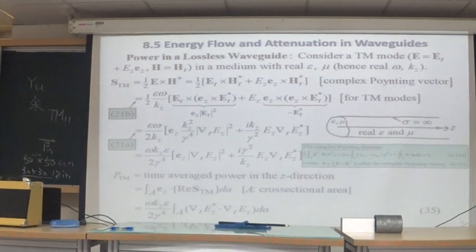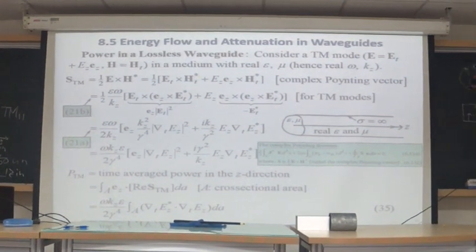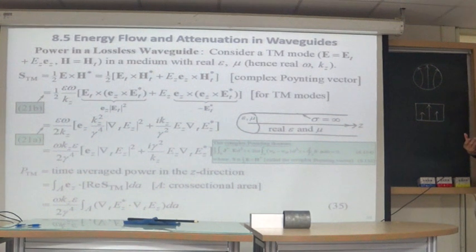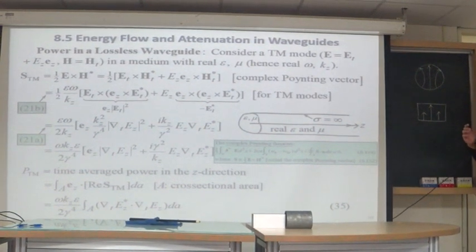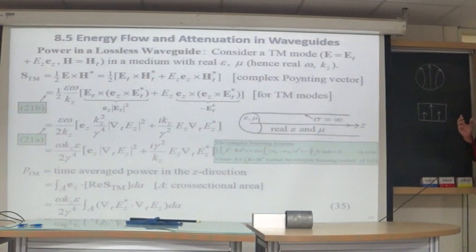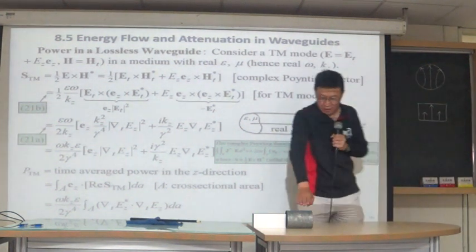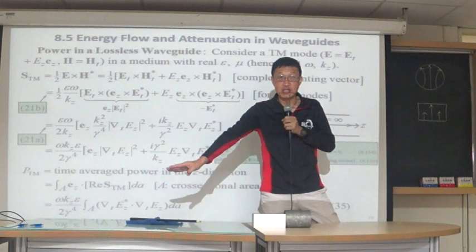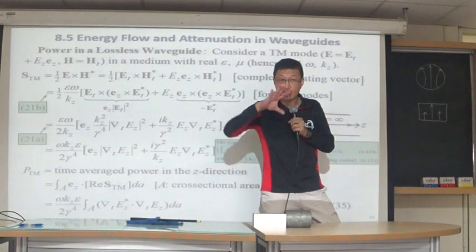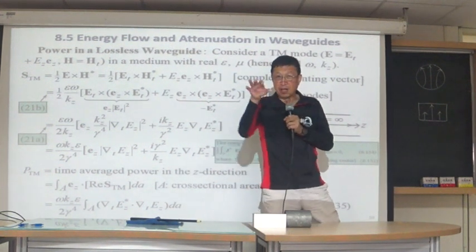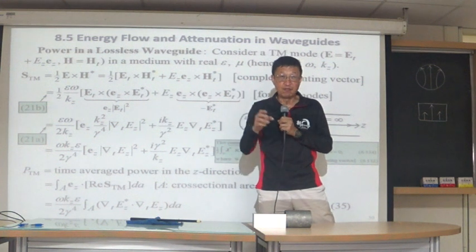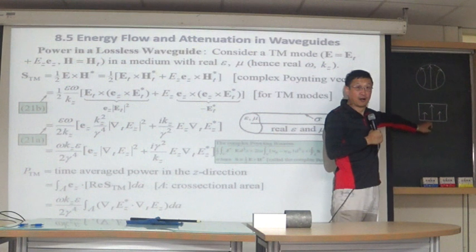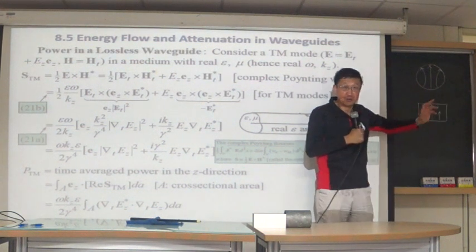Looks similar here and changes. So the idea for mode conversion is taper, gradually change, not sudden change. Sudden change will have reflection, just little transmission. But if you change little by little, gradually, then you can convert this one to here. You have a chance to do that.